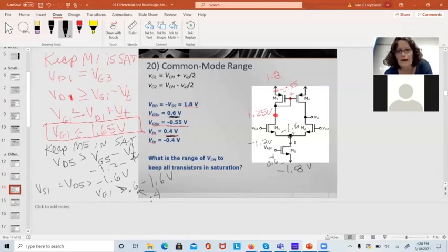To keep it on at this level and maintain linearity, it would be 0.6. So 0.6 minus 1.6 is negative 1. VG has to be greater than negative 1, but I could have it at negative 1.2 if I just barely kept it on.